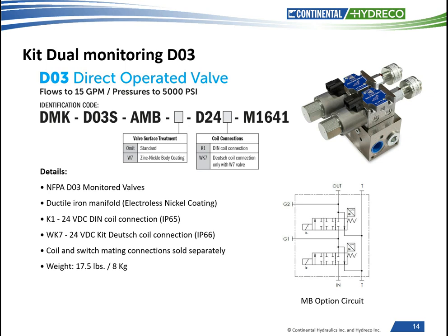In the parallel circuit, if either valve is shut off, the outlet port is connected directly back to tank, draining the outlet port back to no pressure, no flow. So regardless of which valve gets shut off, the end result is the outlet is connected back to tank. That's the parallel part of the circuit.